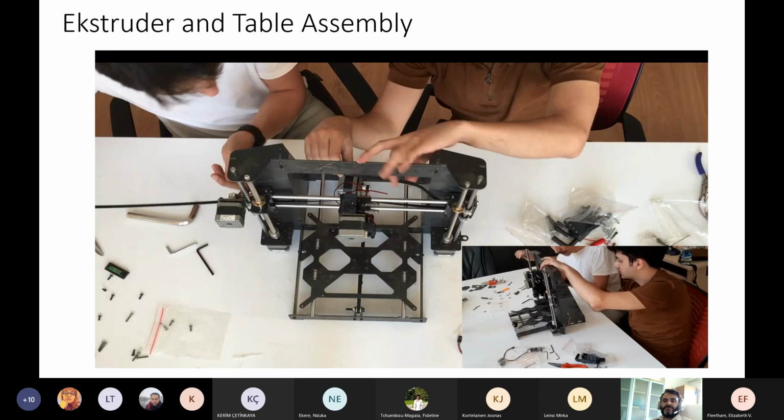With this axis, we can position the extruder head, and as I mentioned, positioning accuracy is very important. In general, the resolution in an axis transmitted by belt and pulley is around 100 micron, and slightly less than this in an axis transmitted by worm gear or ball screw. Of course, the tension and flexibility in the belts that transmit the motor movement are important in determining the resolution. So this is the kinematics in this printer example.